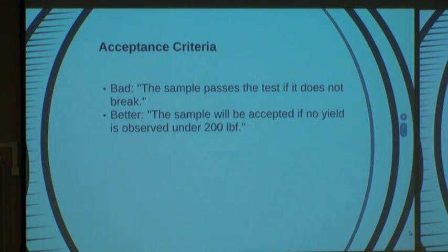acceptance criteria should be based on some objective measure, or at least some logic behind them. So if you're creating a skyscraper and you say it should withstand 50-mile-an-hour winds, that 50-mile-an-hour requirement should be stated beforehand, and it should be based on some intelligence, right? So you measured wind speeds in this area, or this is the maximum wind speed that's occurred here in 20 years, or something intelligent. You don't want to leave it up to chance.